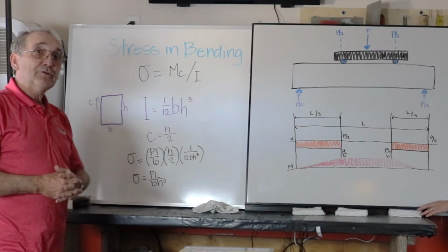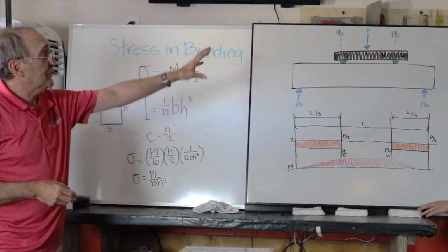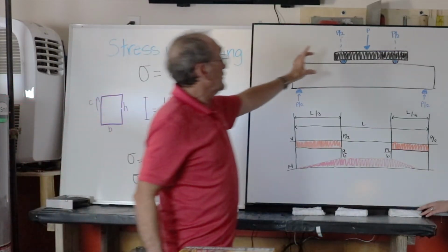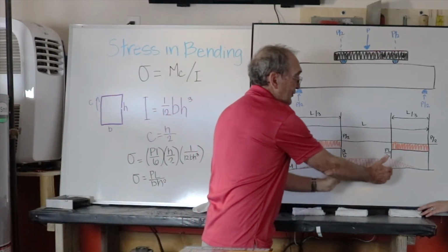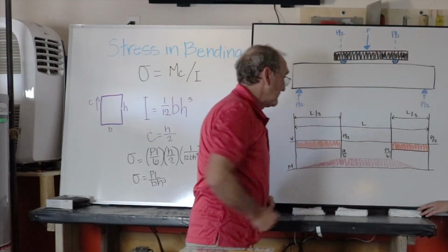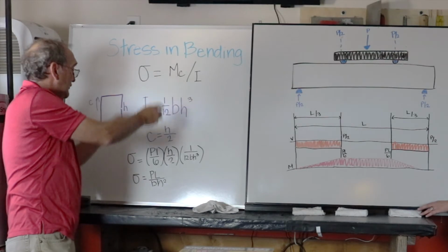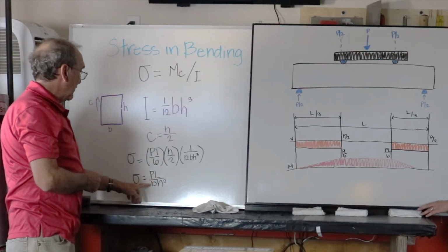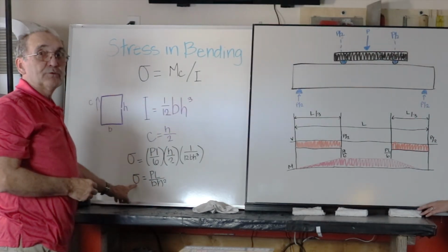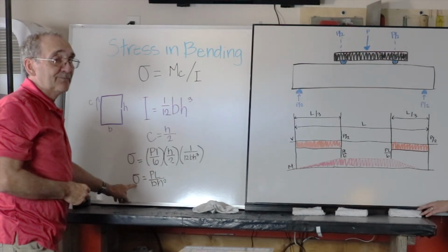That's it. This is a pretty simple test to understand. You have to understand how the boundary condition works to simplify the stress state. Once you know the stress state, plug it into the stress in bending equation, simplify it algebraically, and get what is known as modulus of rupture in ASTM C78.